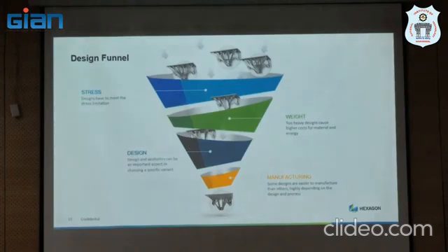On top of it, if you want to add your other aspects also, you can add them. You may say that you want to optimize for only one material. You may optimize for cost also, you can add it here. So this is a complete DFAM workflow, starting with the stress through to the manufacturability.